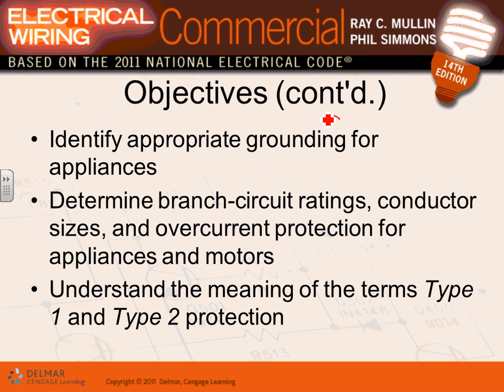Grounding. Every time you talk about electrical equipment, guys, I told you many times, you probably remember that there are two hazards associated with the science of electricity, right? The shock hazard and the arc flash, arc blast hazard. The shock hazard is the reason why we ground a system, because we're going to protect people from a shock hazard. So if you imagine you have a water heater, an appliance, you have to ground it. You know why? Because if you're holding on to that water heater, do you really want to be electrocuted if accidentally the electrical water heater frame becomes energized? So grounding is essential for all the appliances.